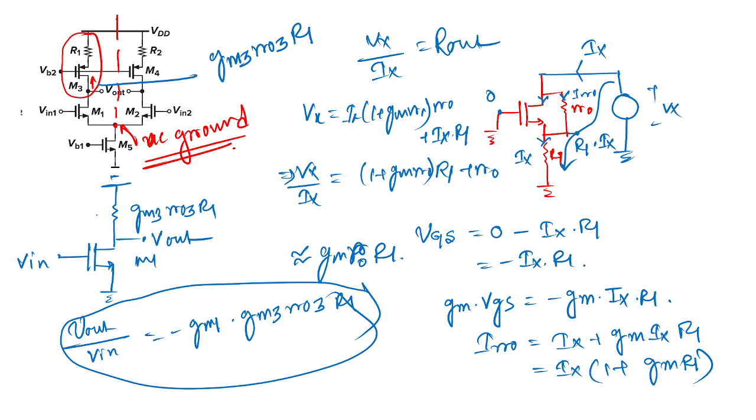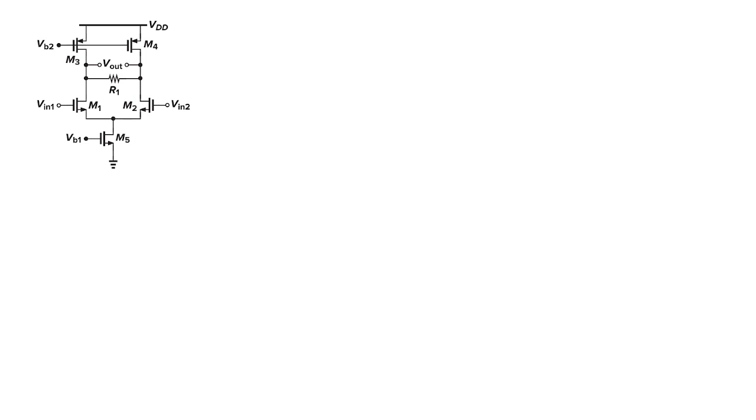One thing you must do before coming to this topic: you must know how to find the gain of common source, common drain, common gate. If you remember those formulas or know how to derive them, then it will be easy for you. Otherwise, later some big circuit will come, and if you go for deriving in each and every circuit, it will be difficult for you, right? So now let's go to the next problem.